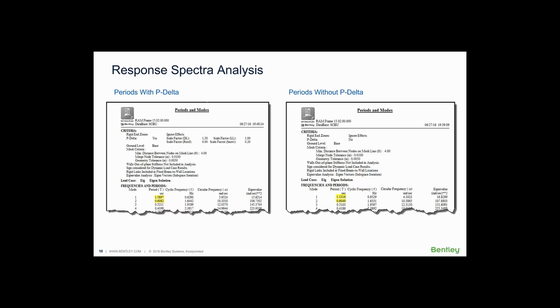Somebody has a question in regard to an approach that I've heard is sometimes used, and I've never done this before. The question is, is it reasonable to run an analysis that includes P delta effects for all the other load cases that are part of the seismic combination, and then combine the results with response spectra analysis of the lateral loads?